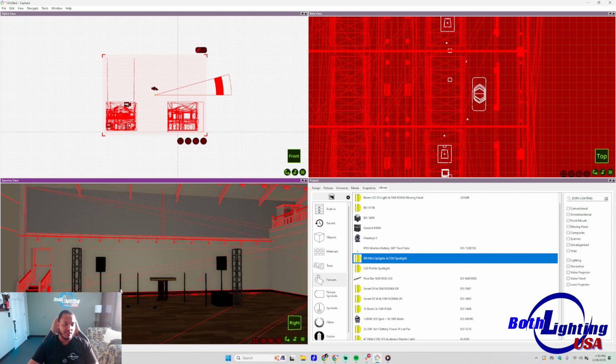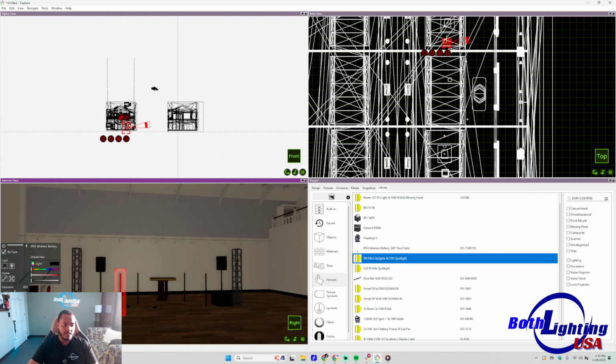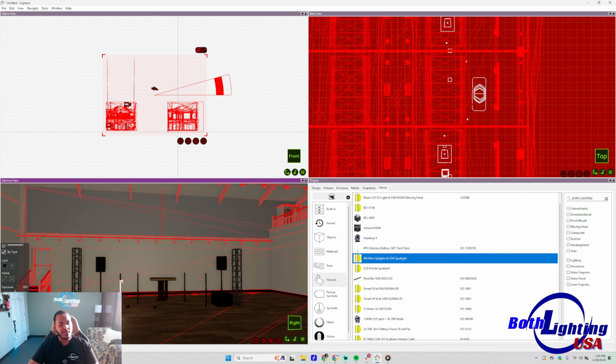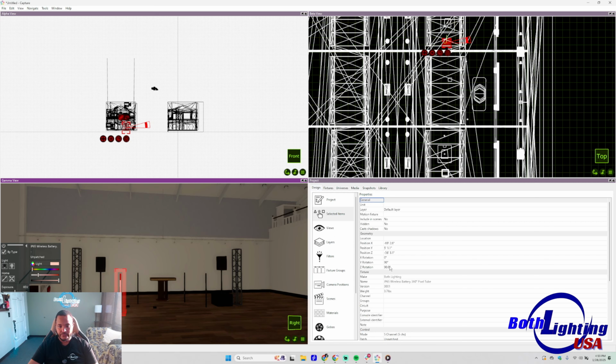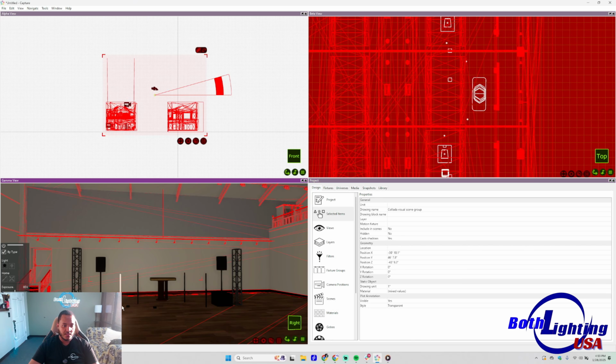For any of your fixtures that you bring in, if you want to see how they look or just turn them on, you can hit the little power button, and it'll pop up some settings for you to add in some manual settings here. So I just went ahead and turned that tube on. And now this also shows that my tube is upside down because of the black base on the bottom of the 360 tube. So what I'm going to go ahead and do is swap my rotation to 180 or -90. So now you can see my orientation of my tube is corrected.